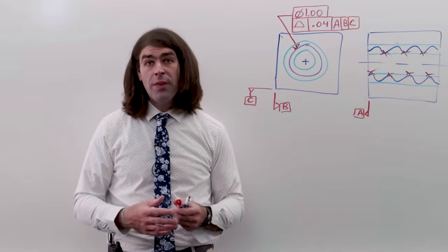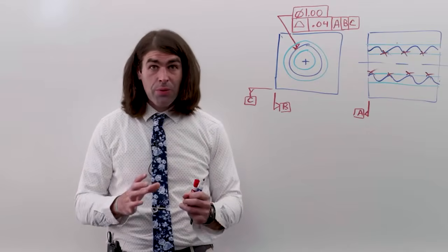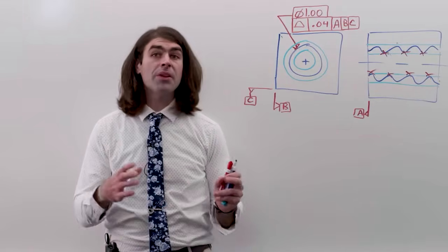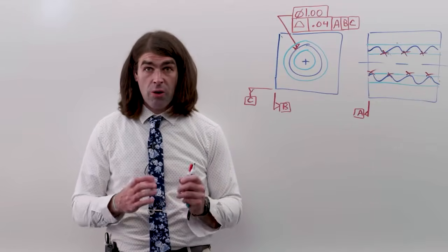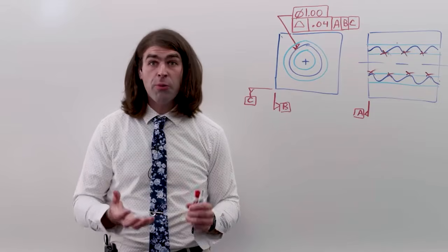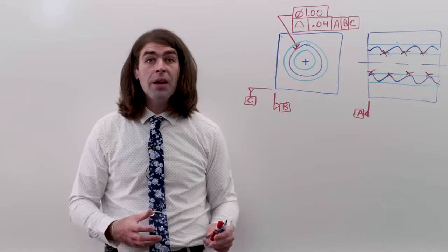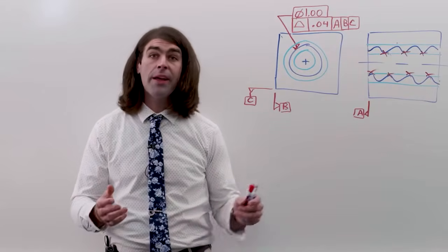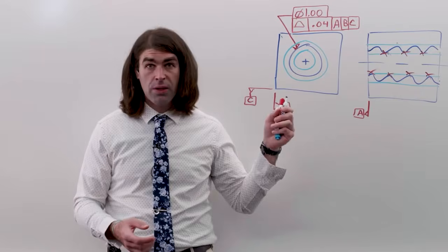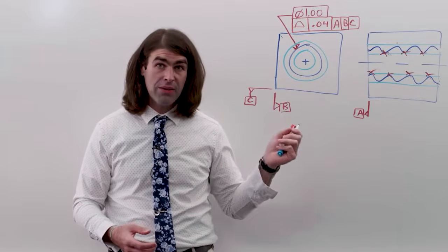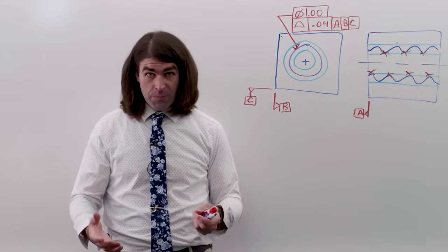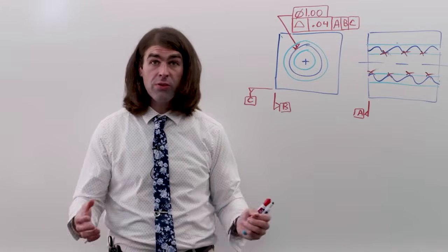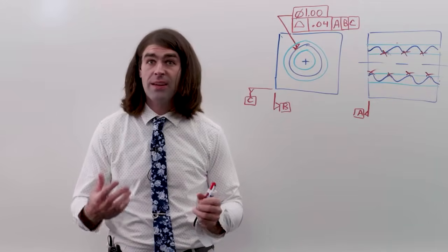Now, one thing position does is separate out the location of the feature from the size. So say you had a hole that needs to take a ground pin and have a very tight fit, but it doesn't matter so much where it is. You can do that with position, where it'd be more difficult to do that with profile and certainly more expensive. And then the other way as well, you could have a really tight location and then a really loose size tolerance if that was necessary.